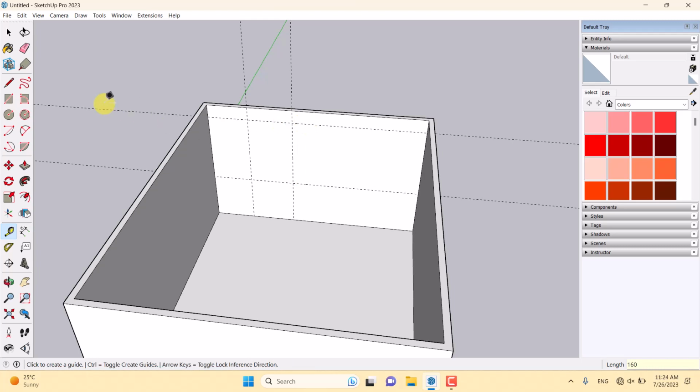After typing all of them and creating them, I'm going to click on the rectangle option and draw my window place. Users who work with 3D Studio Max know that we have a modifier called ProBoolean. It helps you create voids in your wall or make your wall empty.